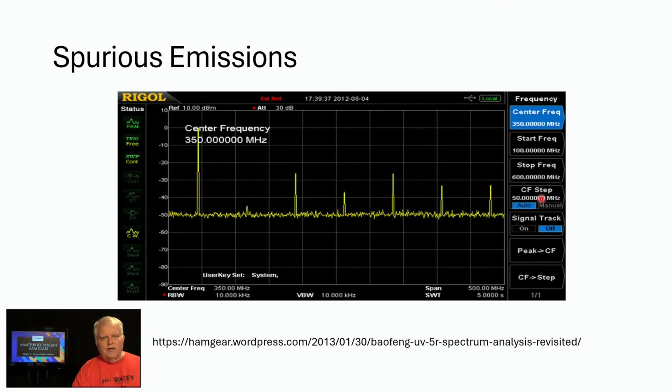This is in the frequency domain of a signal here. This is the primary signal. This is what we want to be amplifying. But if it's overdriven, you get all these other spurious signals on harmonic frequencies above the fundamentals. So don't overdrive the amplifier.